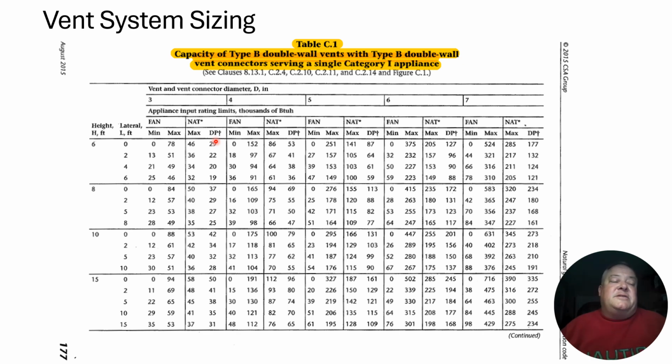People might say to me, because I did tell you, how often are you in a building without exhaust? But I will tell you, you get into some bigger residential types, and I'll give you an example. Let's say that we've got a 5-story apartment building, and it has a boiler room on the main floor that basically supplies the heat to the entire building. Well, that boiler room has an outdoor air supply coming right into that room. So because there's nothing exhausting air right from that room and it's bringing fresh air right from the outside, we can actually use the max column for that application.